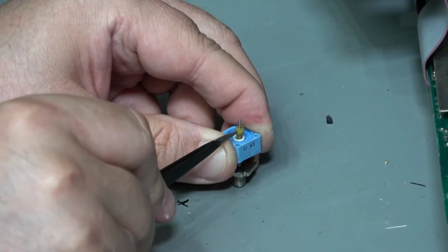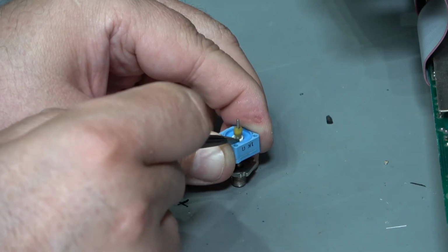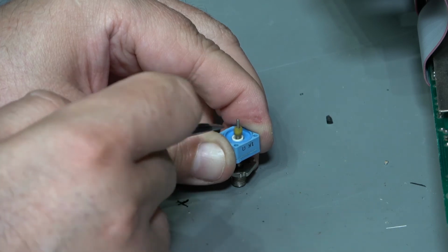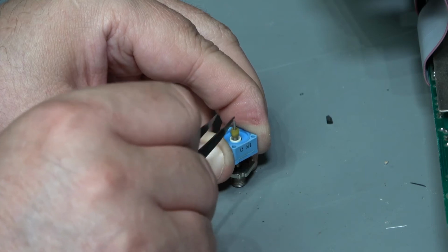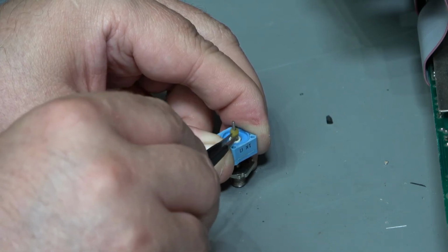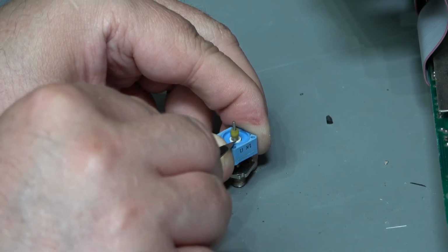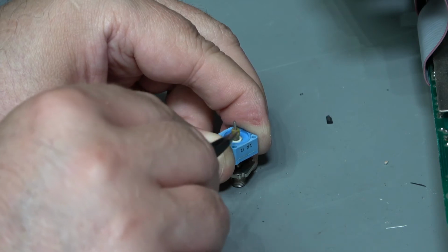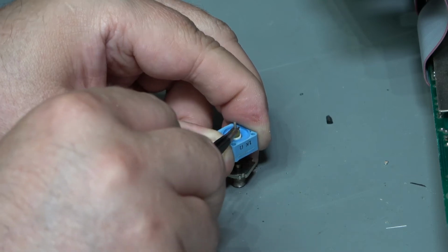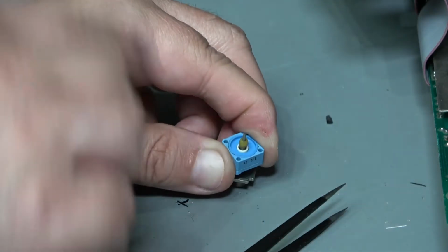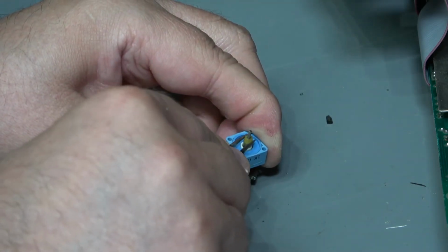So I'm pretty sure our problem relates to this little plastic piece on here, which is like a friction mount that pulls spring loaded back into this bottom piece, or you push it forward and you're pressing it into the back piece. It seems to be gunged up with quite a lot of greasy stuff, so that's one problem. The other problem is it was actually sliding around on this shaft, so there was no way it was ever going to pull properly back into this back piece. So I've attempted to just glue it in place to stop it moving, because it will not friction fit anymore, that is for certain. There's not a lot of room to get activator in there to make it go off very fast, so I'm having to hold it in place and apply some pressure.